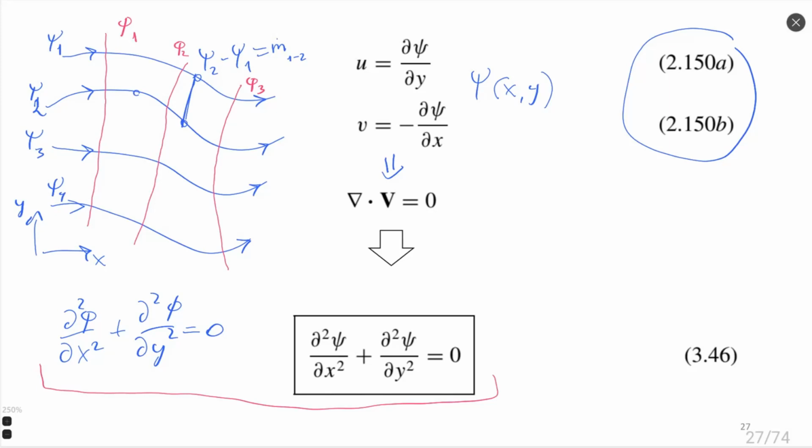The answer is, even when the equation describing the flow is the same for both of these functions, it's important not just to solve this equation, but also to apply boundary conditions to these equations. The solution of a differential equation is a function of boundary conditions. And the boundary conditions in the case of the streamline function are different from the potential function.